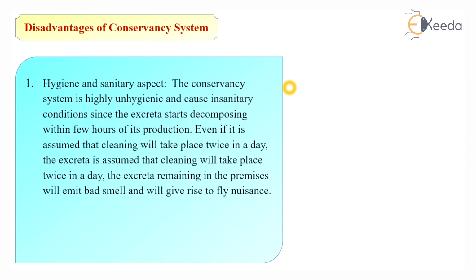Even though this system is economical, it is not recommendable due to various disadvantages, such as hygiene and sanitary aspect. The conservancy system is highly unhygienic and causes insanitary conditions since the excreta starts decomposing within a few hours of its production. Even if it is assumed that cleaning will take place twice in a day, the excreta remaining in the premises will emit bad smell and will give rise to a fly nuisance.